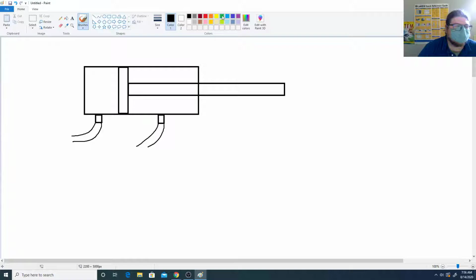So as the hydraulic fluid goes through this tube into here, hydraulic fluid will come out of this side. And depending on what pressure you're pushing into here, the rod will extend forward in this case, and the speed that it extends depends on the pressure and some other factors. So it's the pressure that's going in there and what's the area of this thing. That would be called the extension speed: when you put fluid in here at a certain pressure, the rod starts moving, and what's the speed the rod moves at.